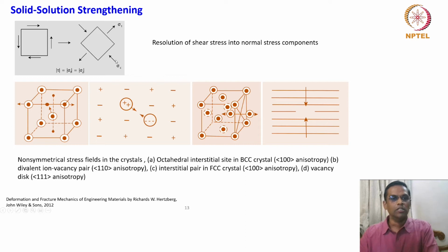Okay. So when you have this shear stress, for example, in screw dislocations, we can consider this is getting decomposed into these kind of normal stress components, and this will have interaction with the lattice energy now. Okay, lattice stress fields. Now we look at the first one, non-symmetrical stress fields in the crystals.